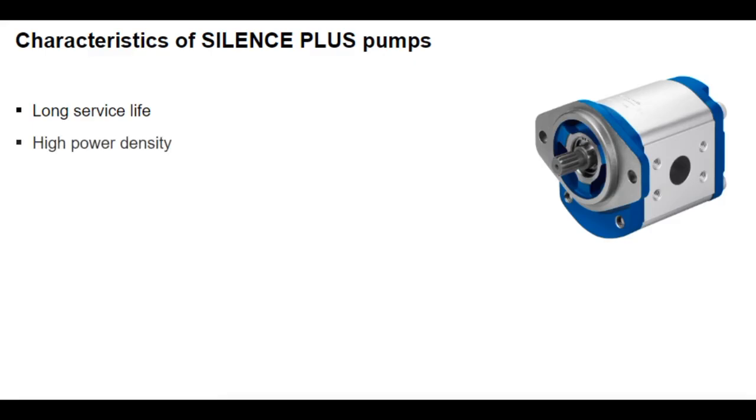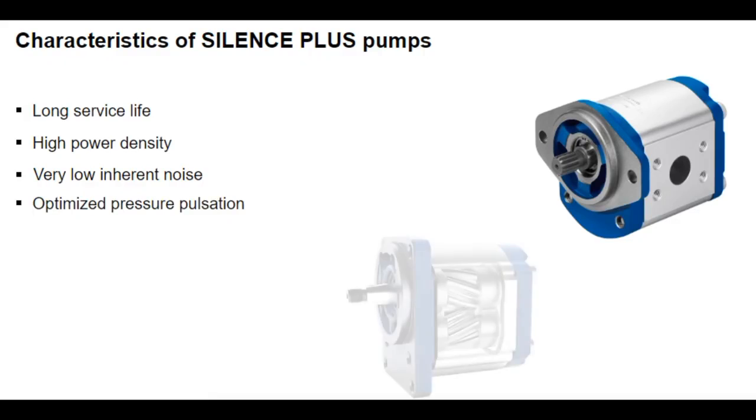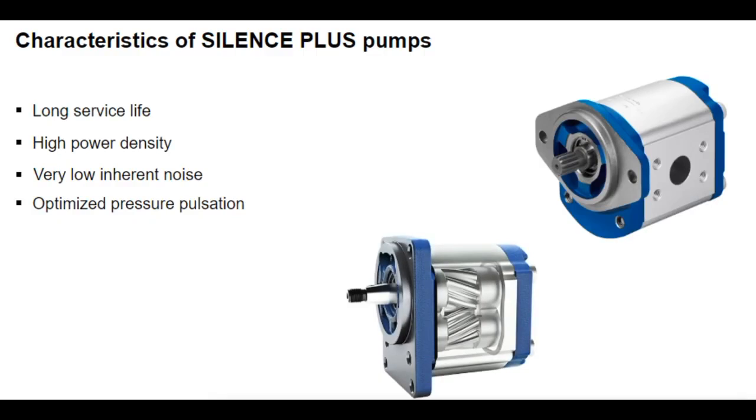Their robust layout allows for high power density. That is, the overall installed size is relatively small compared to their hydraulic power. They can also be designed for harsh operating conditions. The pulsating flow, however, results in pressure pulsations and noise emissions. It is also not possible to avoid.